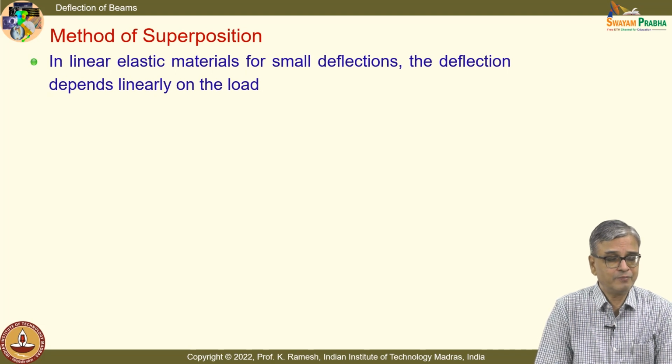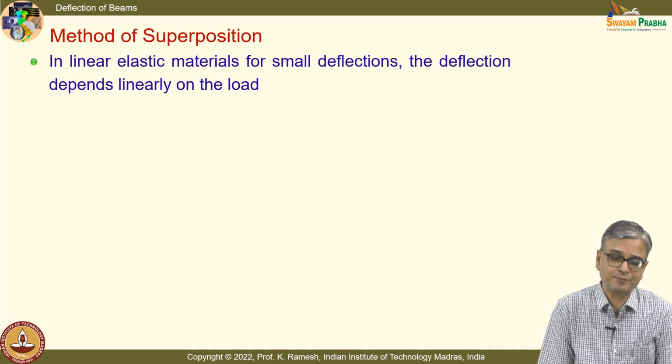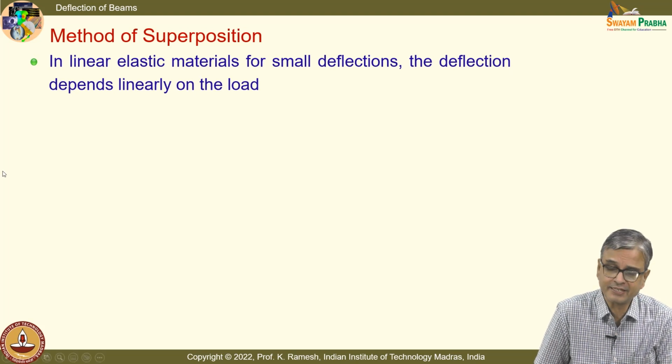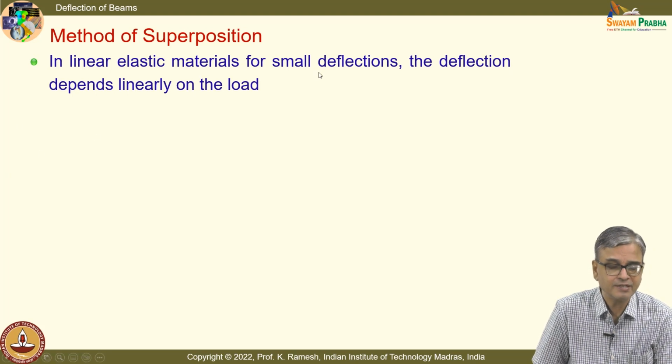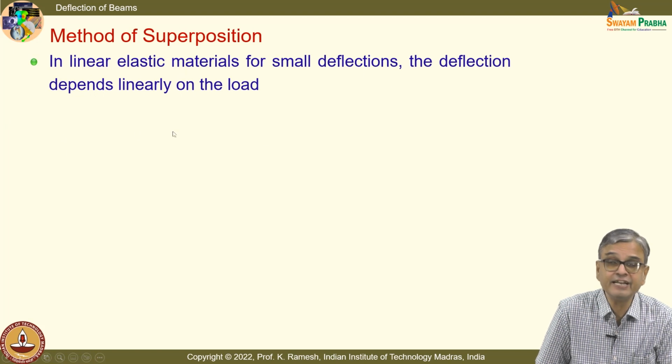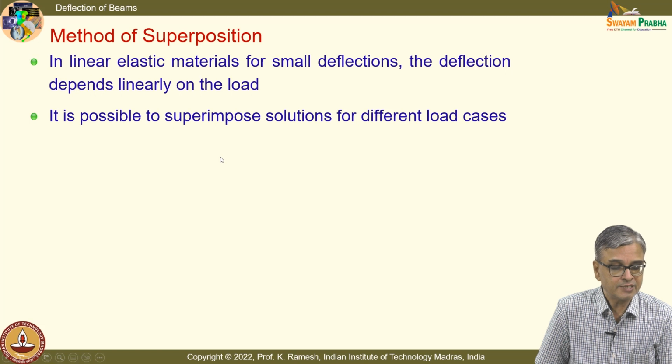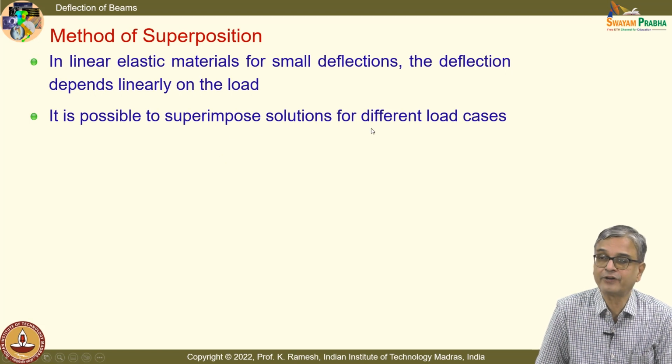So, we would focus more on method of superposition. You have linear elastic materials, small deformation. The deflection depends linearly on the load, that is very important. It is possible to superimpose solutions for different load cases.